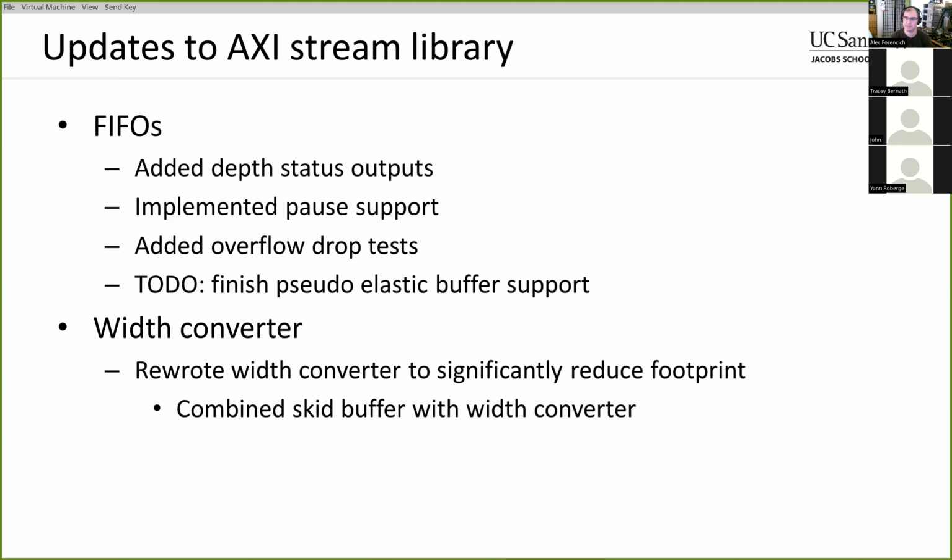We can shrink the async FIFOs in Corundum, which should save some logic resources and, well, save some block RAM anyway, and then we can use that block RAM in the synchronous FIFOs as part of supporting multiple traffic classes.